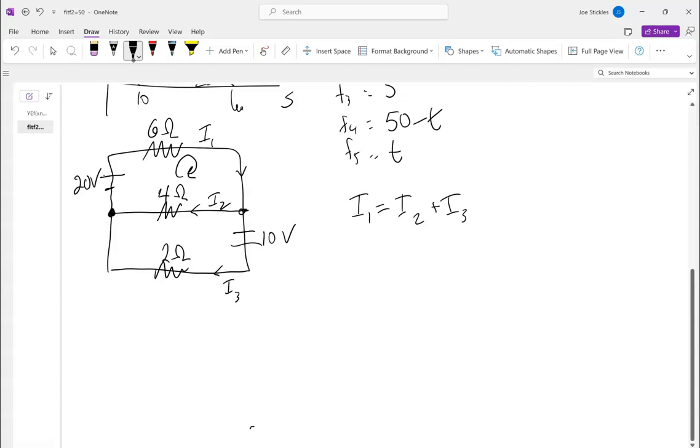All right. So usually, and it's not on this particular picture, we'll just draw a little circular arrow that tells you which way you're going around the diagram to add up everything. It literally doesn't matter as long as you're making sure that you're adding things up correctly. In particular, if I went the other direction, my current would be going backward because you're working against it, right? So this one, it doesn't matter. They've got the vertical line drawn down in the picture, so I'll just say we're going to go the same way, this way.